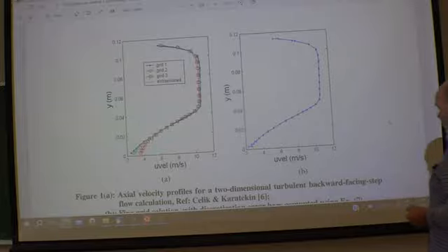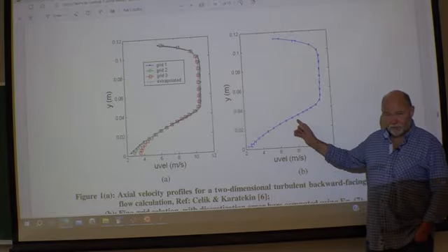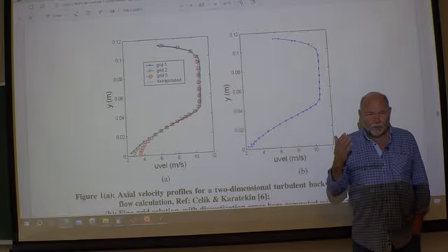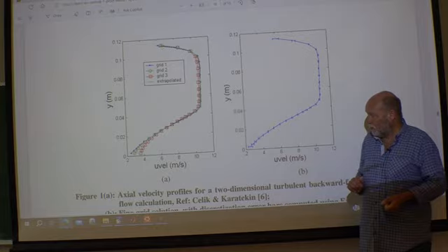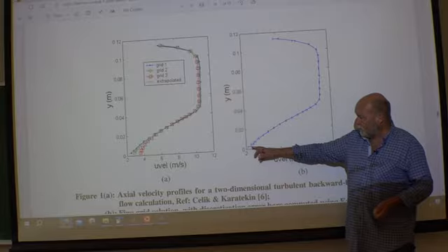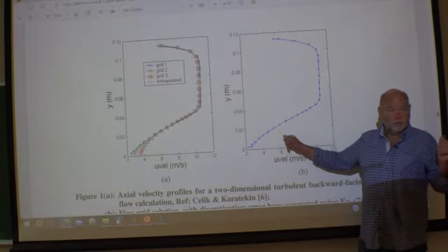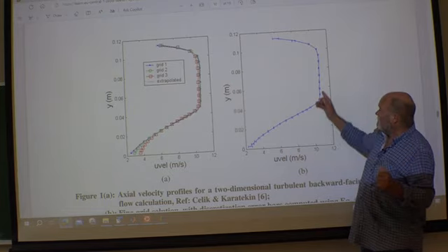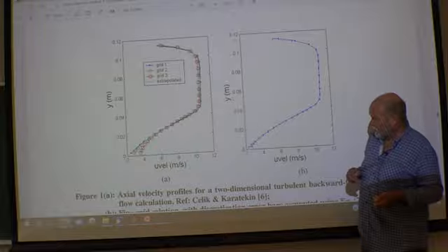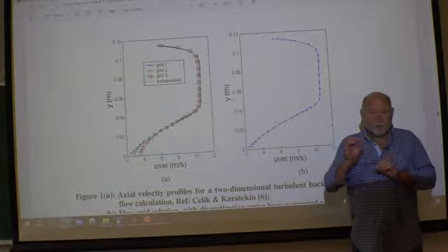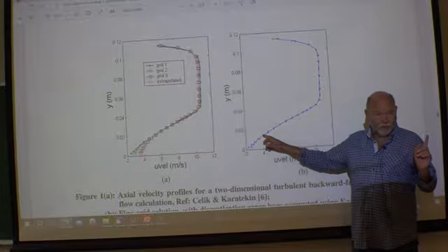First of all, you have to decide where you want these error bars. Then you simulate with 3 different meshes, and you detect the velocities at these locations on all meshes. So you shouldn't have too many. Here they have overdone it a little bit, I think. That might involve a little bit of interpolation, because you need the exact same location for all 3 meshes.